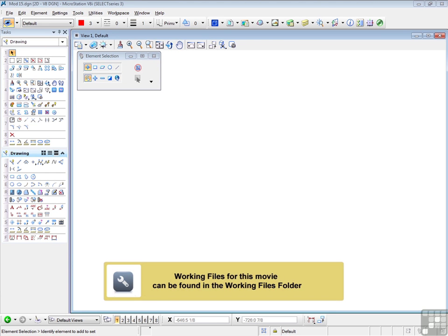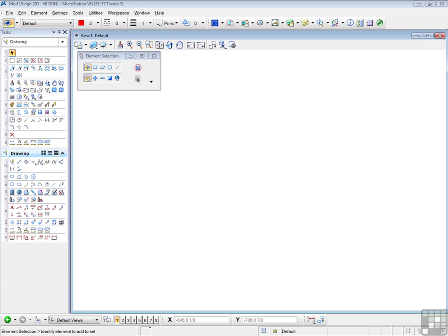The next MicroStation facility to look at is the standards checker, which will check the elements in an open design file for compliance with the settings and standards contained in a DesignLib file. It's usually very important that all elements in a design conform to company standards before being issued to clients or for manufacture. The standards checker will do this, provided, of course, that the elements were placed using the correct templates